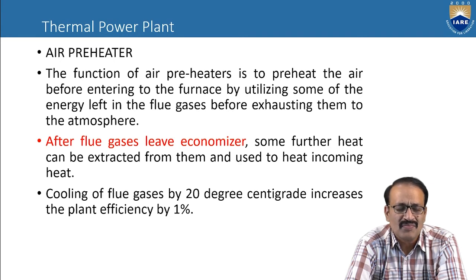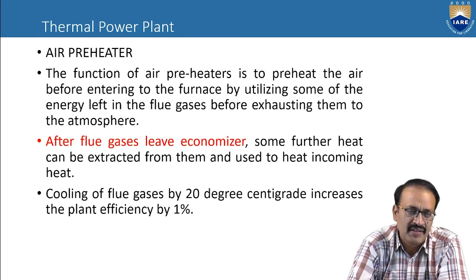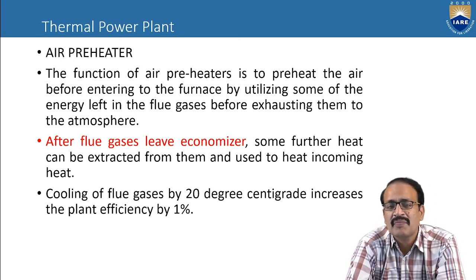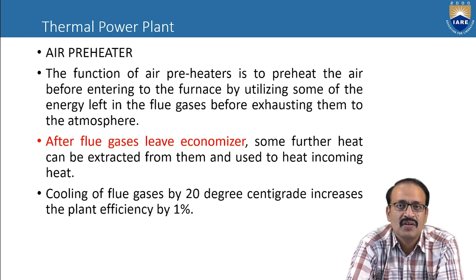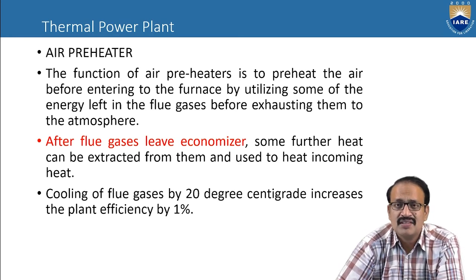Here also the flue gas which is leaving the economizer still has some heat energy in it, and that heat we use for heating this air, and this air is sent to the furnace. So it increases the efficiency.